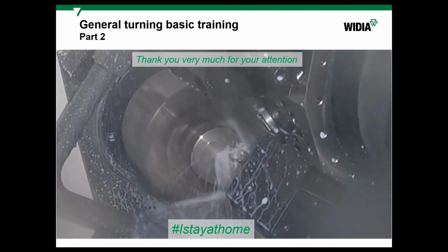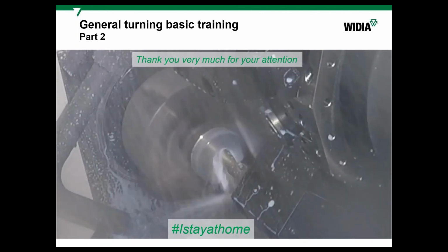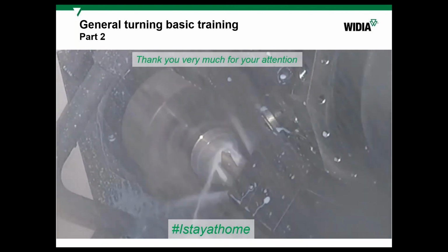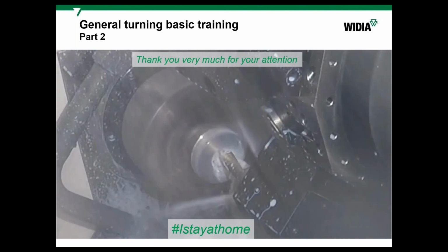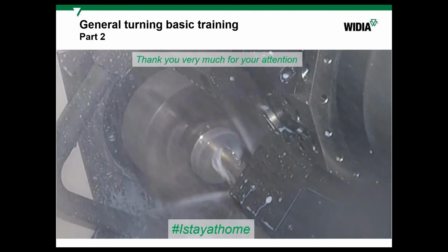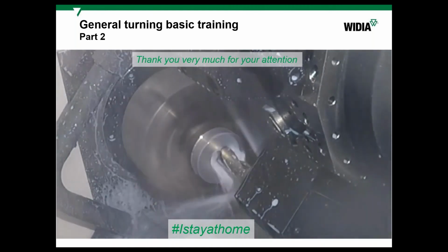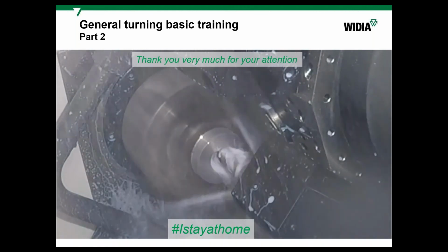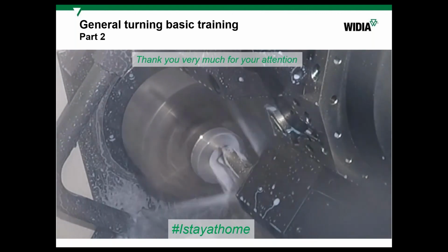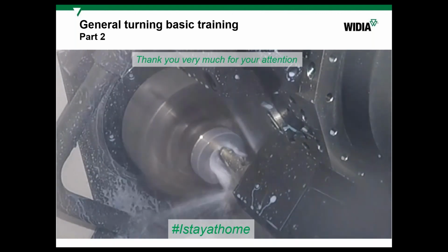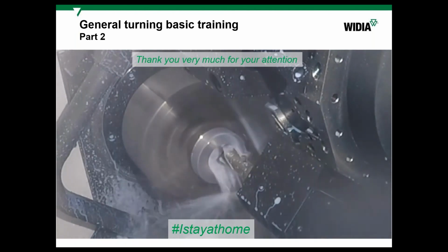Only because of that. For semi-finishing applications or chip breakers, this value usually is different. Smaller on the radius and a little bit bigger, but sometimes not. So it also depends. I'm not a designer of the tools. I know something, yes, but better to ask who designed this concrete chip breaker. But basically, because of RH, it should resist any type of hits, even on the corner.